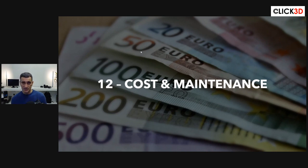On the laser scanner side, manufacturers are going to want you to get the instrument calibrated every year. And calibration is a big cost. It'll cost you thousands of dollars. You send it back, you lose the equipment for a little while, and there's shipping costs, there's all kinds of other things. So unfortunately, from a cost and maintenance standpoint, photogrammetry is the clear winner there. It's definitely more economical than using the laser scanner.